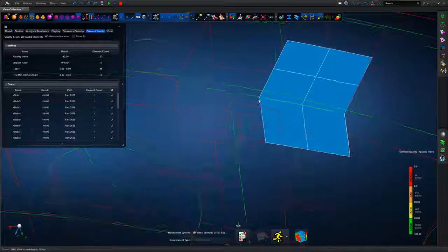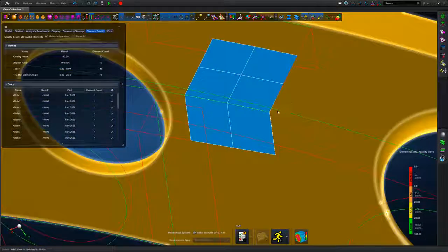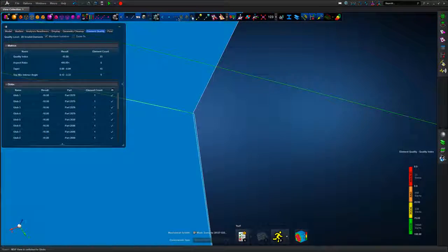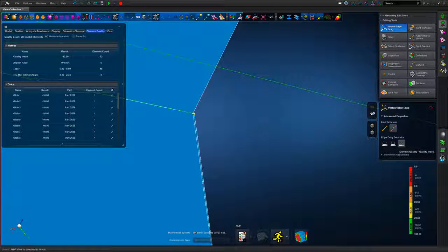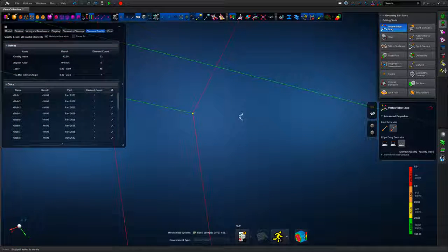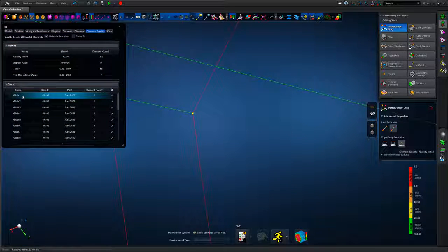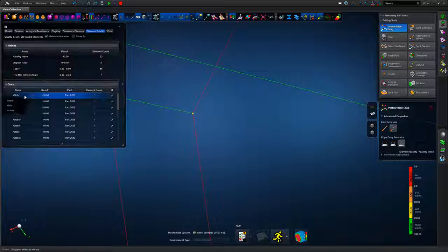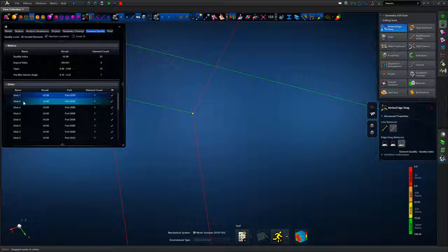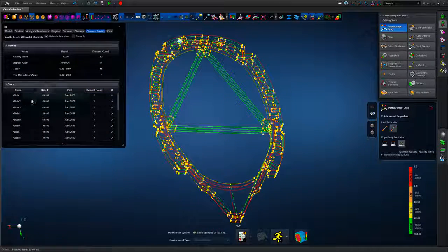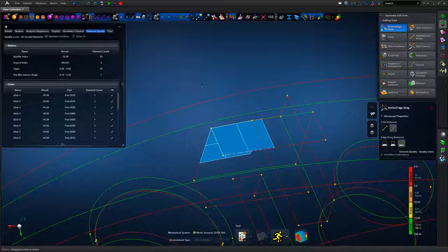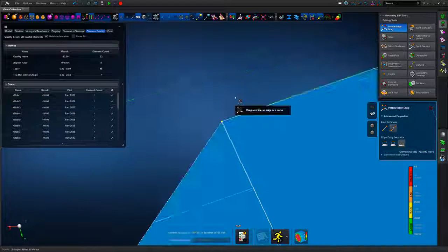So we can just work our way around each particular failed region within the model browser tree, which is showing us each overextension of the mid-surface as a glob, a term used, and we can look through each one of those globs, as it were, to isolate and enhance each particular region where we've got poor element quality. So just cycling through the model.